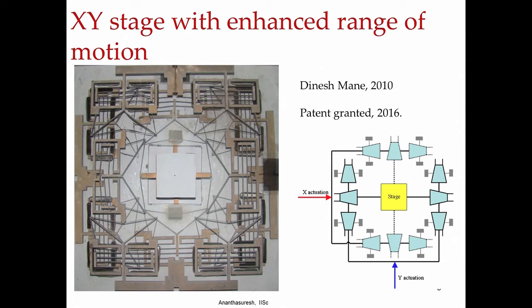They have a DACM and a compliant suspension. This particular thing shows a sliding joint and a displacement amplifying compliant mechanism. When you arrange them in this particular fashion, 12 of them, you get this, or you can arrange them 6 in each plane and attach at the stage, you can get this mechanism.